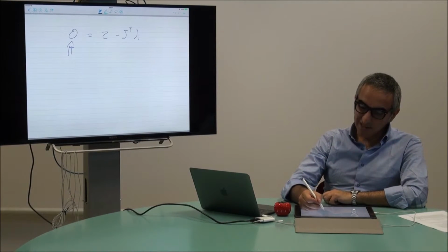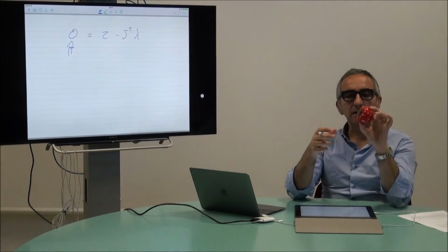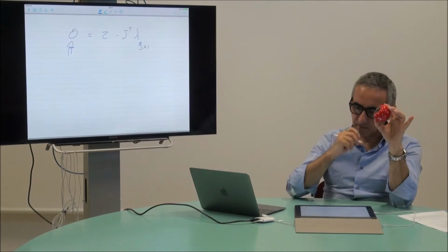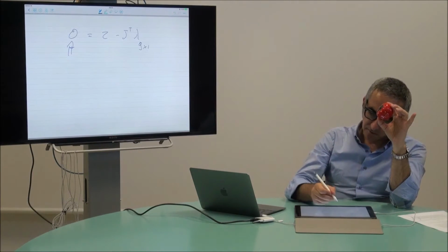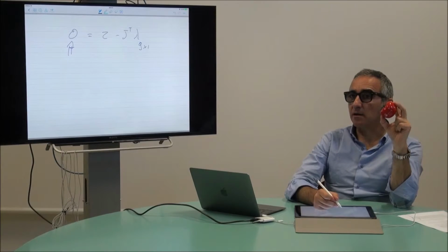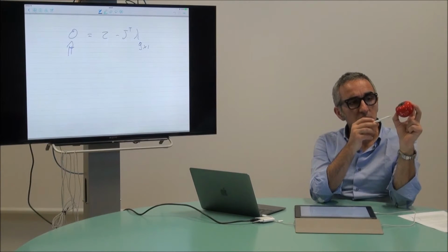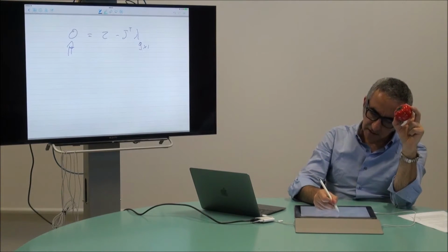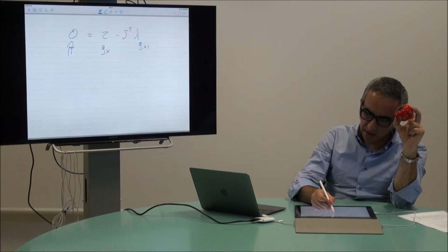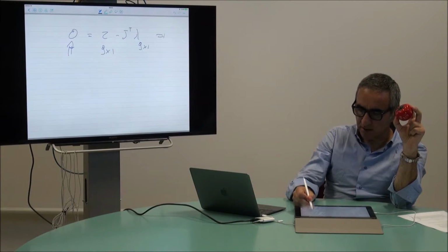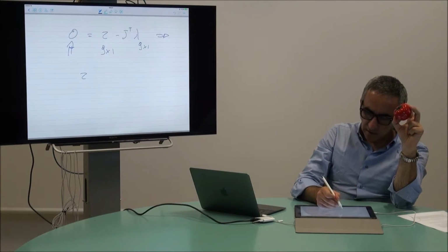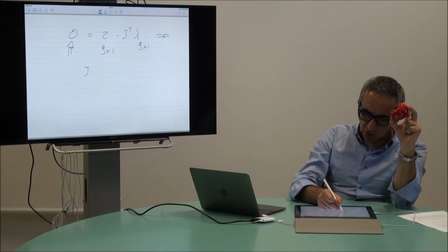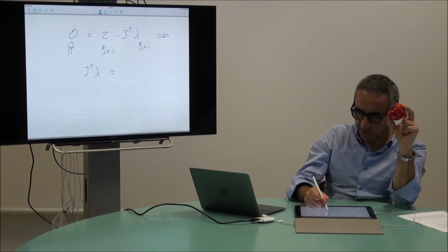consideration, we said in this case you have that the lambda vector is 9 by 1. Tau is 9 by 1, you remember, because you have 3 motors per each finger. So 3, 6, 9. So this is 9 by 1, and this equation becomes J transpose lambda is equal to tau.